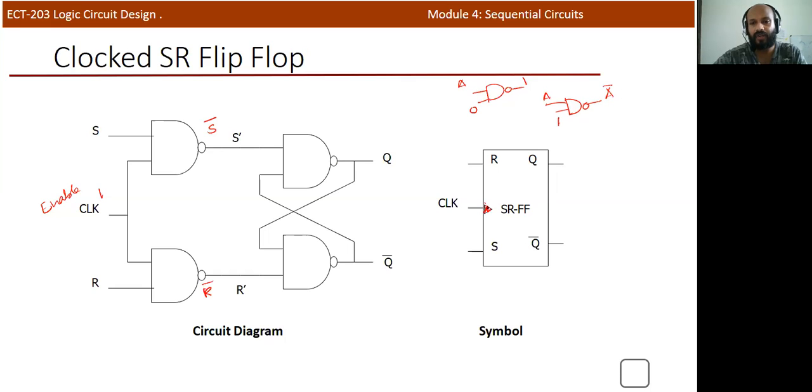If you're not using any edge triggering, we only require a logic high signal. Whenever a high signal occurs, the output changes or the input becomes sensitive, so we don't indicate any symbol here. Similarly, we can put a clock signal, or call it an enable. So this is the clock. Other workings are similar to the previous one.